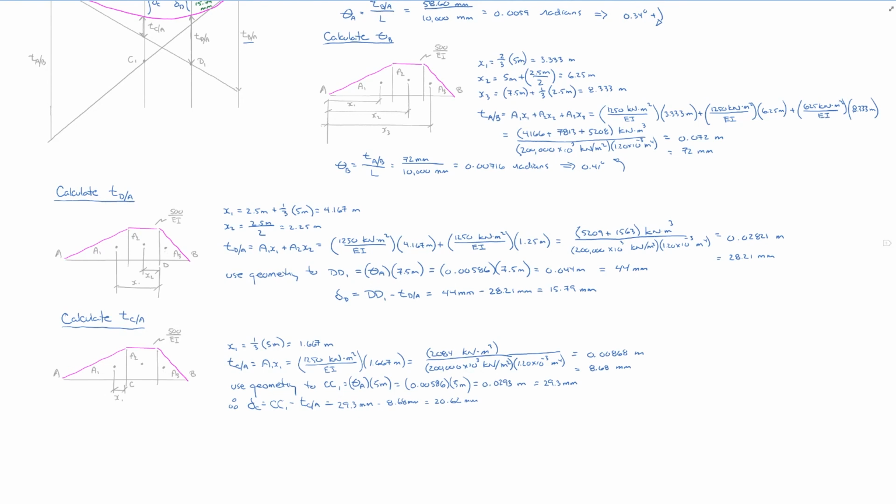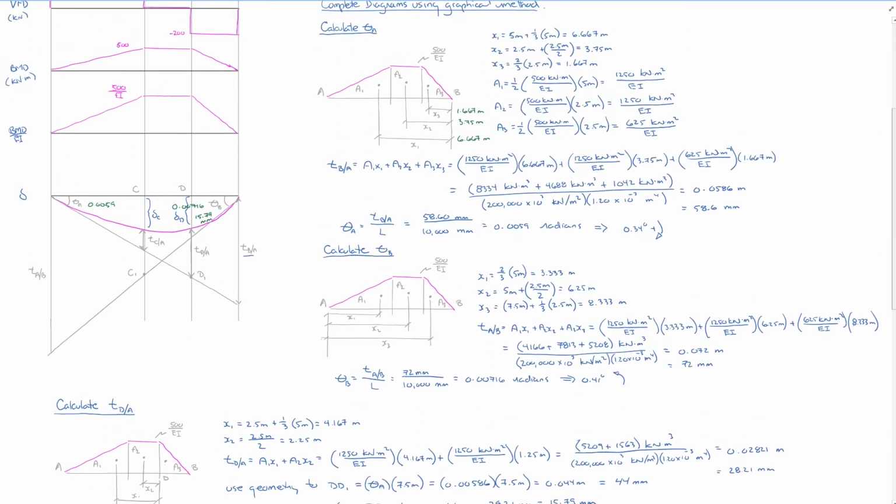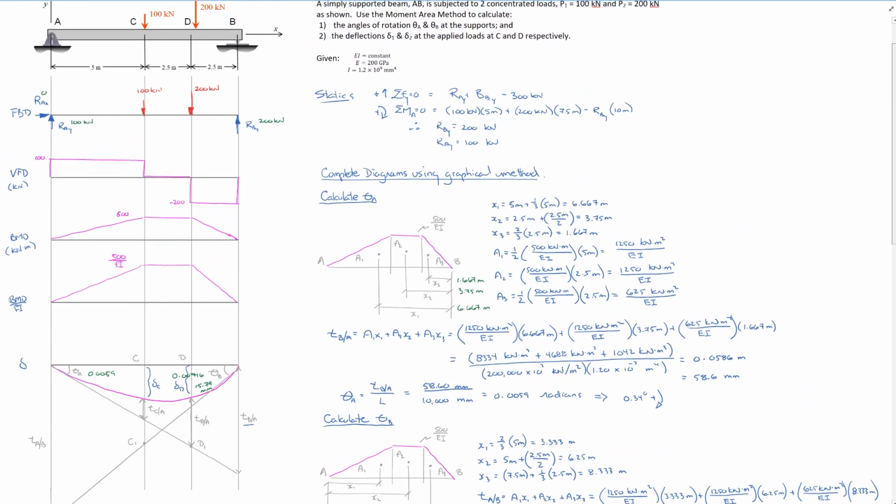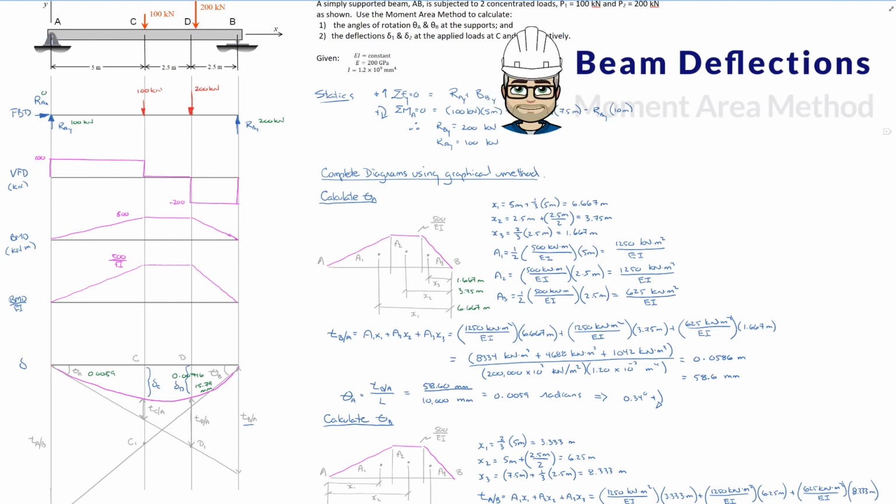And the problem solving for this all happens in that displacement diagram right there. So if you can get to that displacement diagram and decipher it because you can appreciate or understand how important the supports are with where their tangents go, whether it's a fixed support or a pin support, it unlocks the geometry, which allows you to apply the two theorems in order to solve the problem.